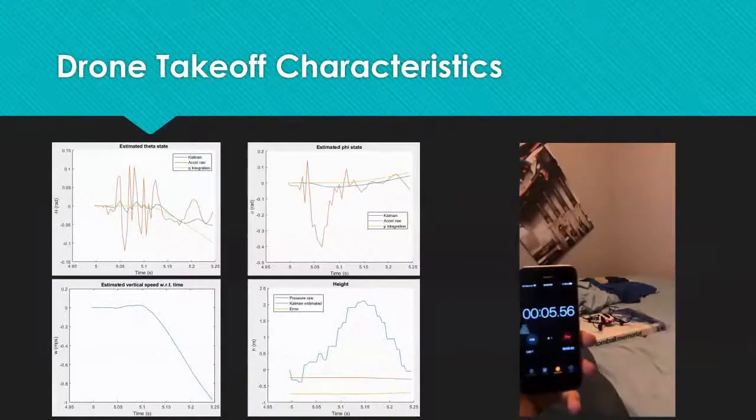For the drone takeoff, just a little more of an in-depth dive. In developing the takeoff phase, all controllers were shut off in order to tune the offset speeds to get a near vertical takeoff. Once the drone had a near vertical takeoff with minimal angular rates, the elevator and aileron controllers were enabled in future takeoff flights. As is shown in the top two plots, there is good angle control during takeoff.